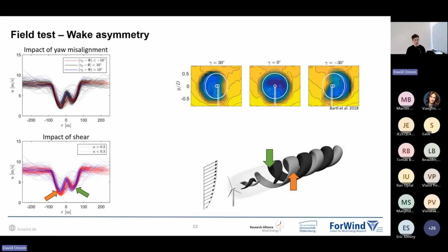Of course, do we define the wake center as just the center of the total momentum deficit, or do we define the wake center in the sense of this middle point between the two semi-peaks, or double Gaussian wake deficit? This cannot even be answered that clearly. I think it's just important in this context to report how the wake deficits that we're dealing with look exactly.